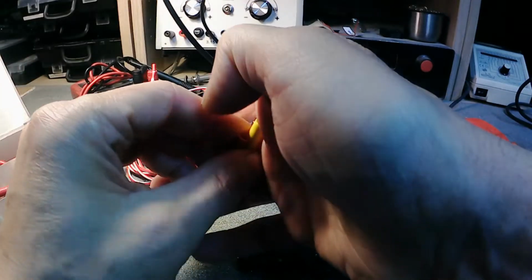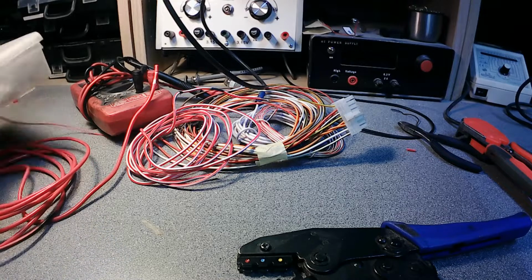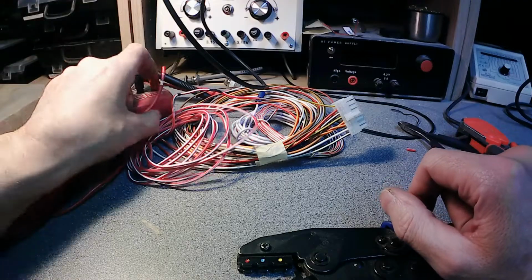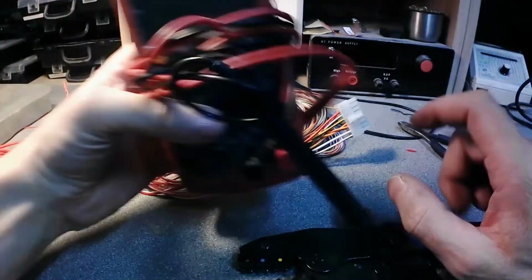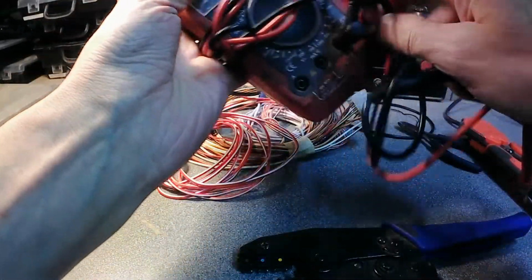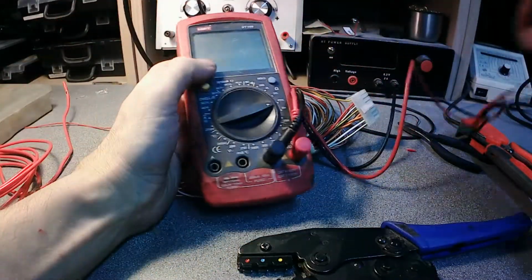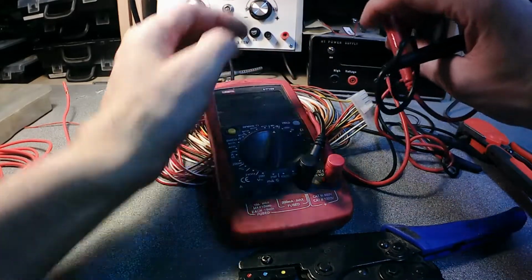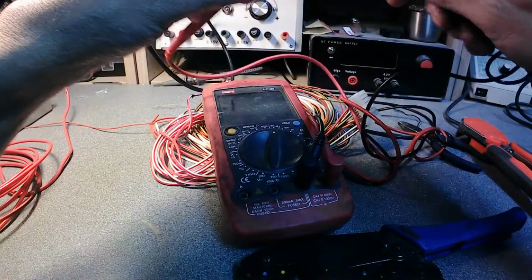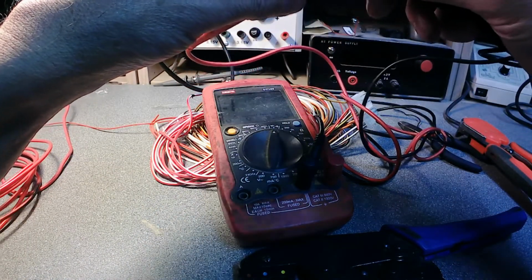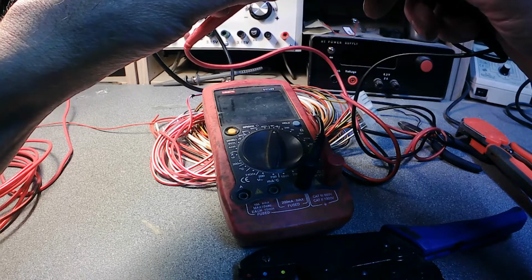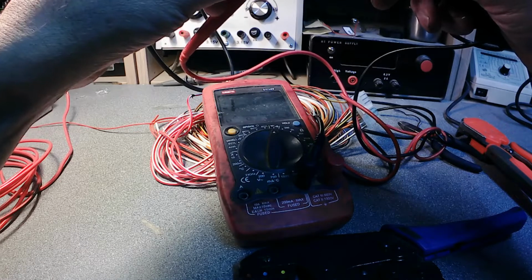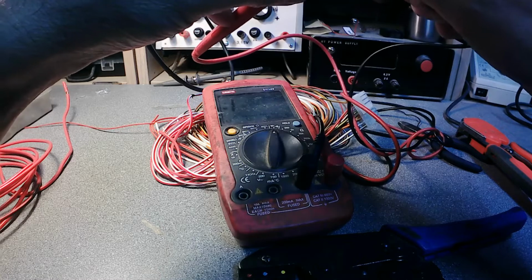Of course, from time to time we use thicker things, but it's not so many, not so often. And maybe the most important but very useful tool is simply a multimeter. You don't have to be good, you don't have to be expensive. The most important thing for us when we build the wiring is this function. We can check if we have a closed loop of wiring or not, and this function has to have a quite loud buzzer.